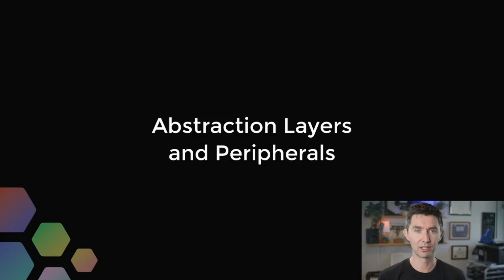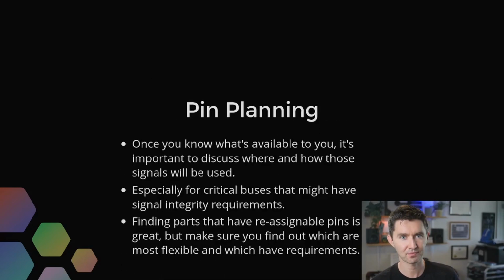your implementation in firmware? And then how are you talking to all the things that are outside and around your device, like sensors, like communication things, if you have an external modem, things like that, and even troubleshooting abilities too, right? So like where are your UARTs? How are you getting stuff in and out of the processing parts of your IoT design?